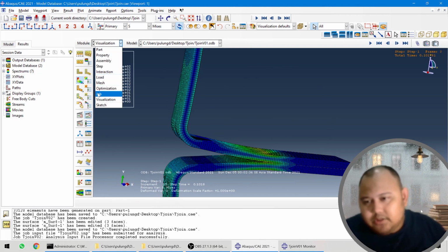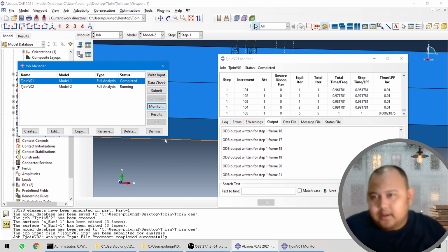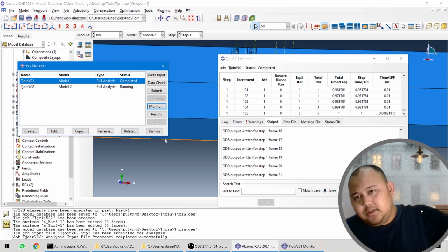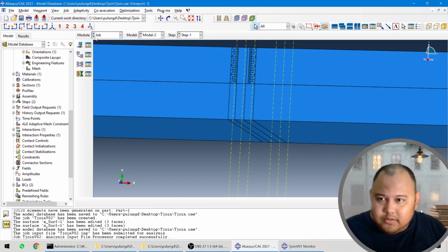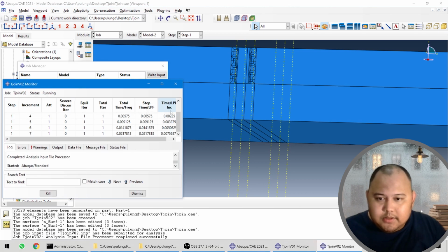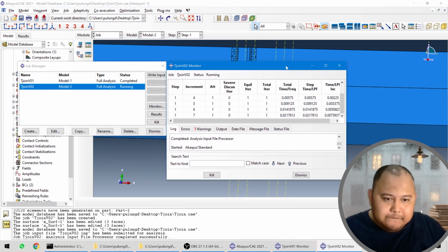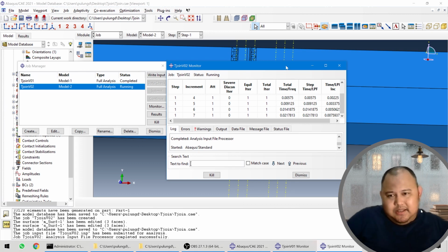Because this one is actually too easy to converge. You can tell, right? 100 increments. So in that case, you can actually increase the K, right? Because it's still very easy to converge. You can increase the stiffness to get the theoretical stiffness, that is quite, goes to infinite, almost infinite. Let's check first. Yeah, this one should be easy, I think.